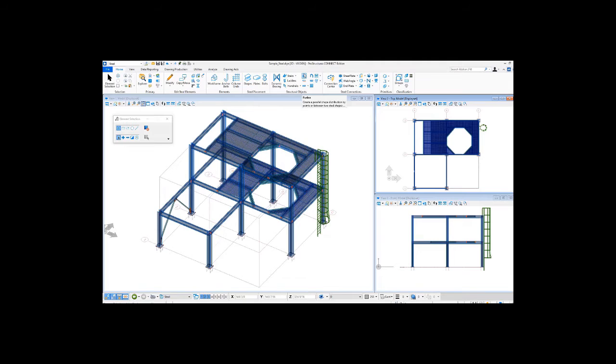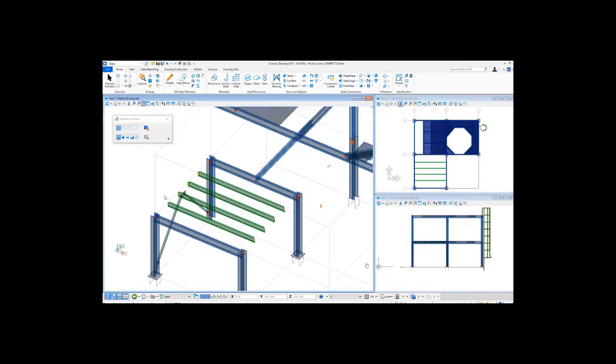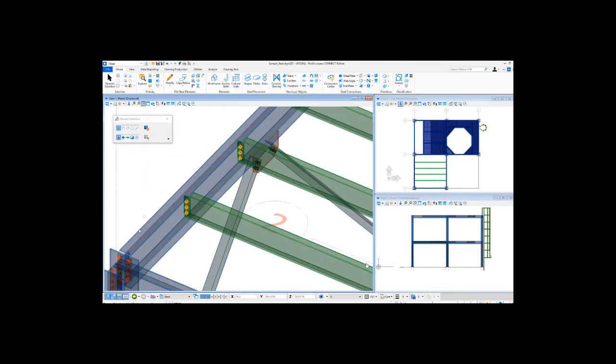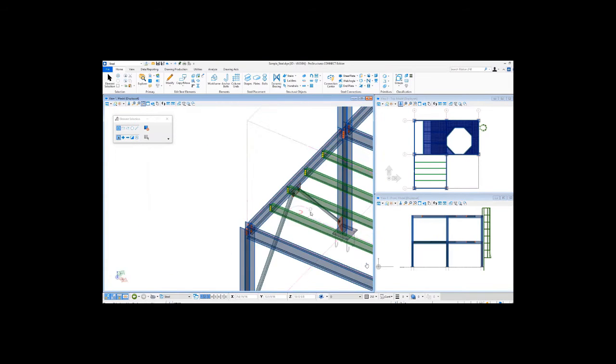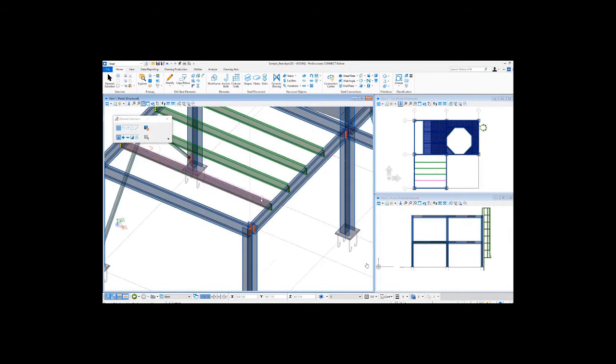So what I plan to show you here is how we can add purlins to this member. Just in this video, you can see by selecting these two beams, you can add purlins. So this is your purlins dialog box, and you can use shear plate connections. These are templates that have been created previously, and once you add those templates, you can see shear plate connections at both the ends of the members that form the purlins, right? Very easy to create such an assembly.